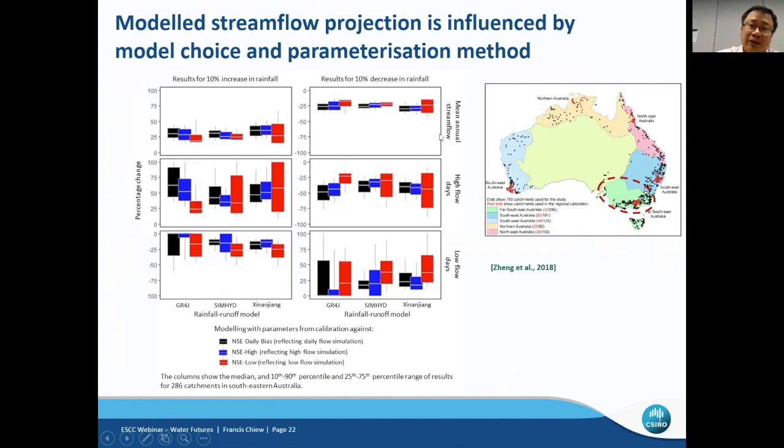So when we're looking at mean annual streamflow, I probably get quite good agreement regardless of which model I use and how I go about calibrating the model. But I was talking about a Taylor distribution earlier on. If I'm looking at the high flow characteristics or the low flow characteristics, the results do matter on the choice of hydrological models and on how I parameterize the models. So there's some work that needs to be done by hydrologists in figuring out the most optimum approach for the different applications we might want to use the models for to make future hydrological projections.